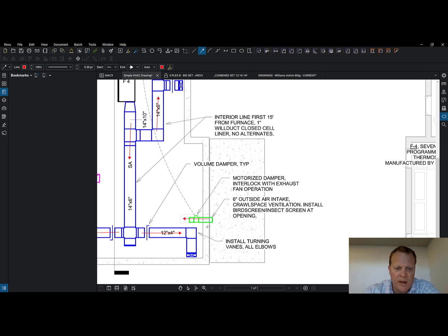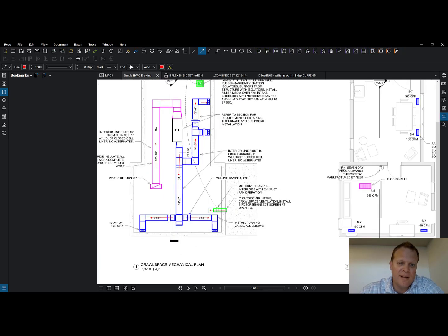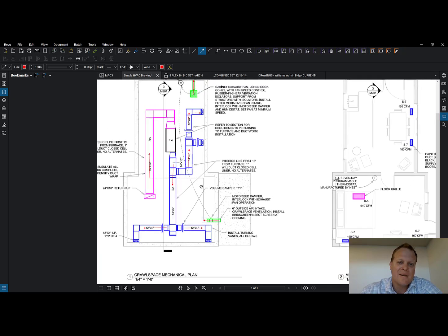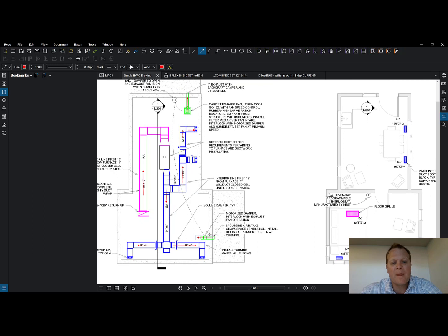Well, why would we need that? Well, you just do. We already covered what outside air and exhaust air does. But obviously you need some combustion air going to this furnace. So you need this to definitely work. But the humidity in the space, they don't want the humidity to get into the insulation in this. So they're going to remove the humidity as well.